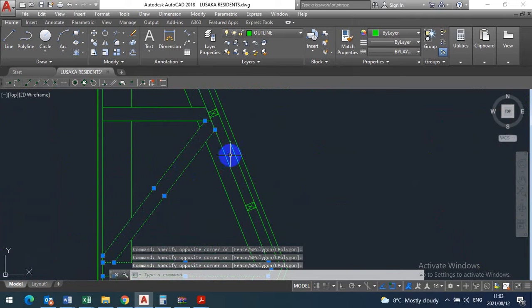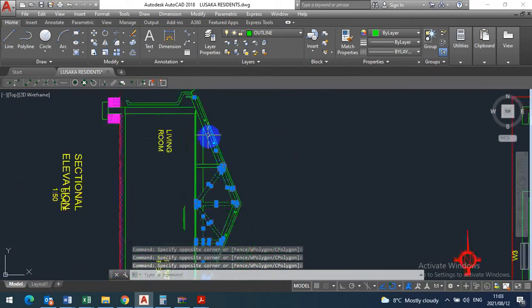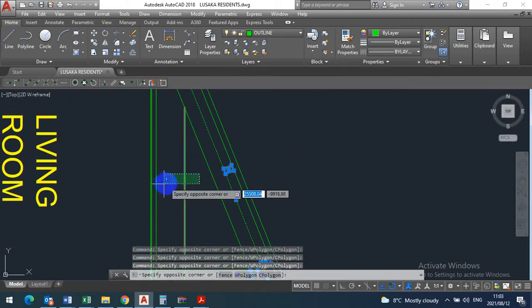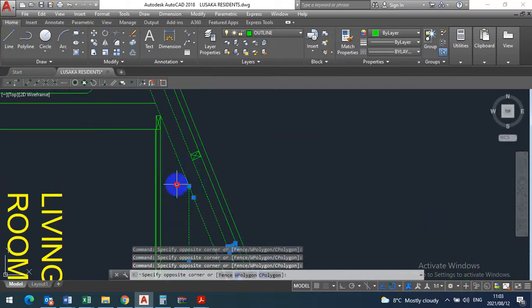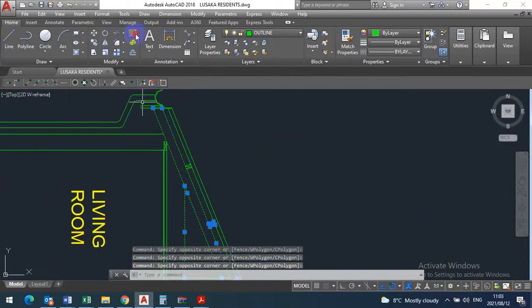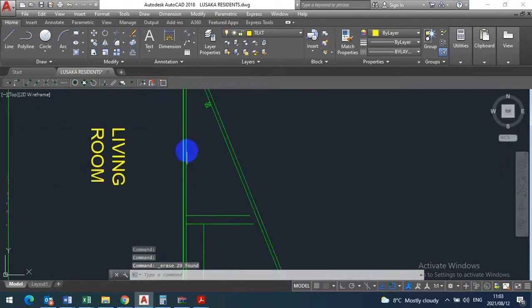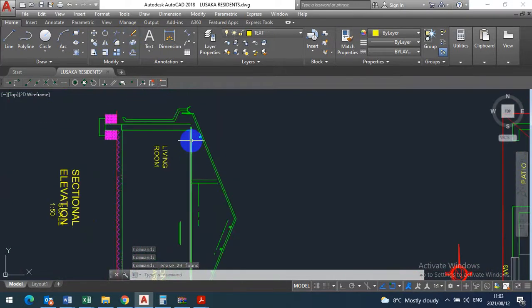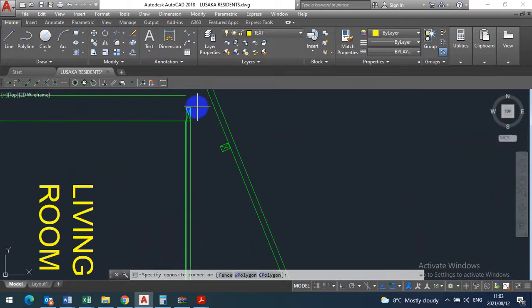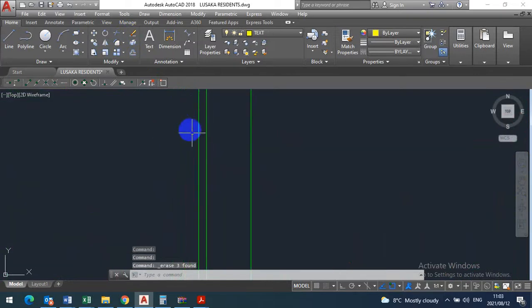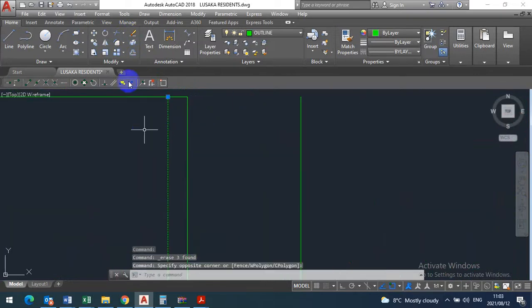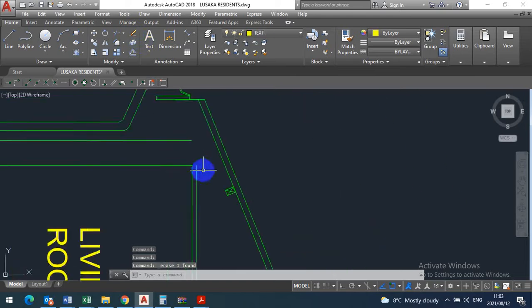You're working from an already drawn drawing. Remove the purlins. Only those must be shown in sectioning. Remove, delete. Okay, the ceiling board you're not going to see. What you're going to do is delete this. Okay, the top of wall you're going to leave.